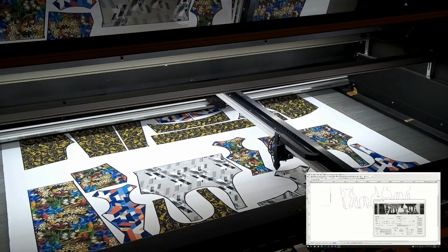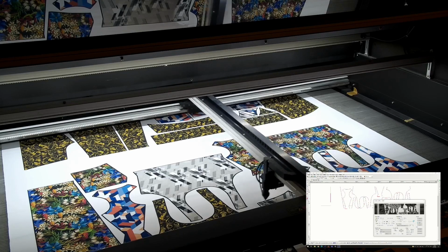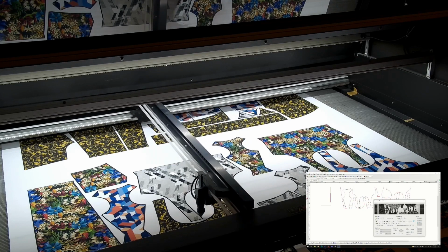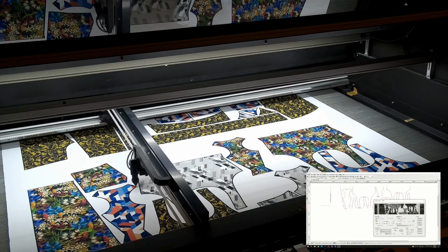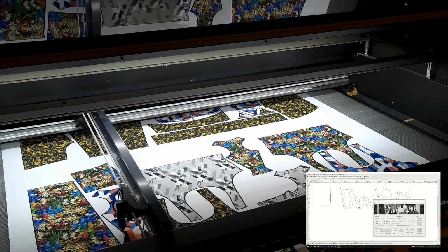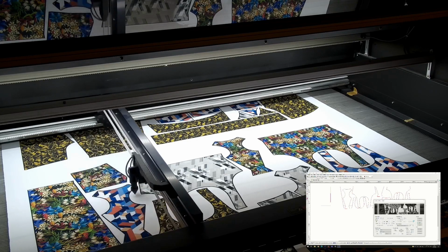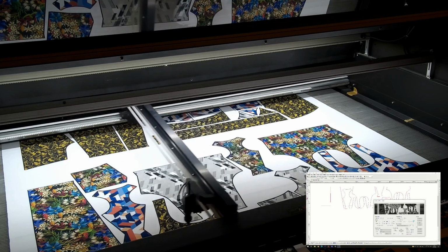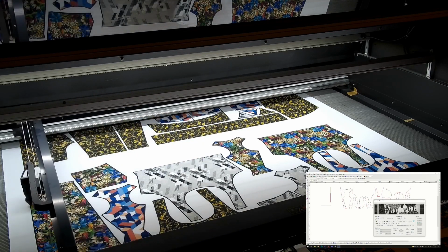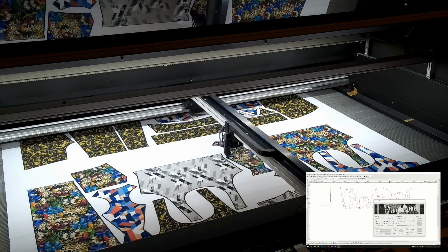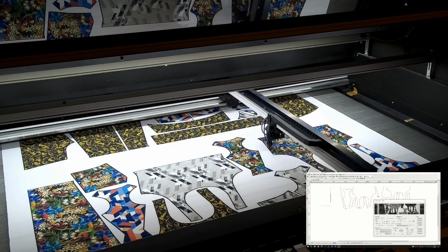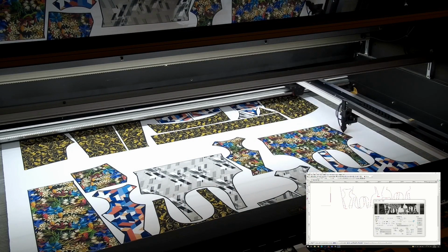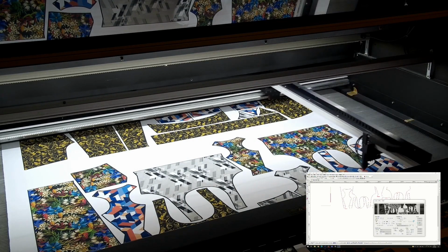It was moving forward and it was already cutting using the laser. I set up my workflow so that it's going to cut 3 mm on the inside. I could have just set 0 and then it would cut on the outside. Now, what you need to be aware of, while this is running, you need to have somebody in front picking up all the pieces. Otherwise, you need to have boxes arranged before your machine to catch everything. Otherwise, they will drop on the floor.